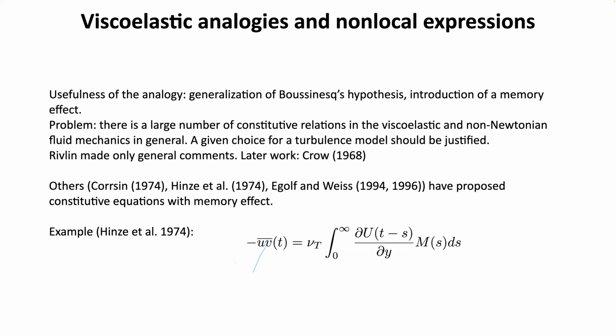Is it still the case that Reynolds stress tensor models, with one model per each term of the Reynolds stress, are less expensive compared to this kind of tensorial development of the Boussinesq hypothesis, or do they become comparable in terms of computational cost? You mean computation cost between the full Reynolds stress models and nonlinear eddy-viscosity models? Yes.